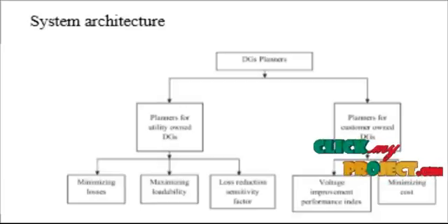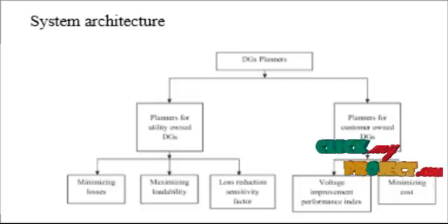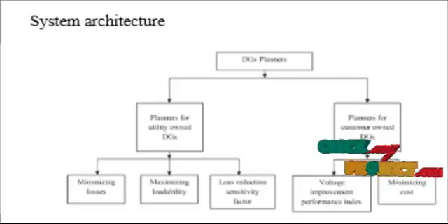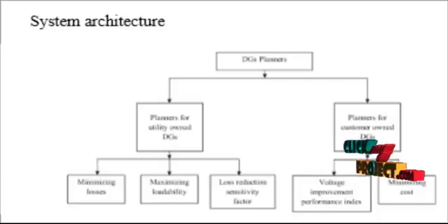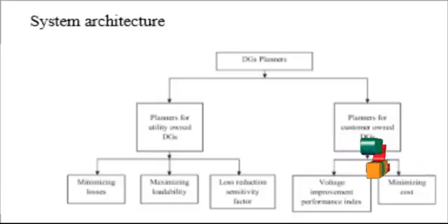The optimal location and DG placements have been identified with maximization of system loading. With the integration of DGs, the loadability of the system increases. The maximum system loadability has been determined with 5 available DGs at optimal locations. The line flow in the cases without and with DGs is observed, and the remaining 2 and 3 DGs cases are presented.